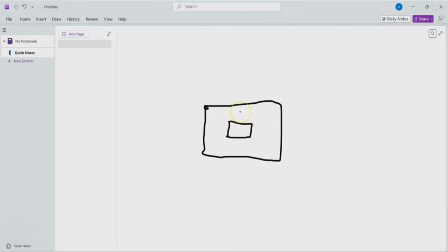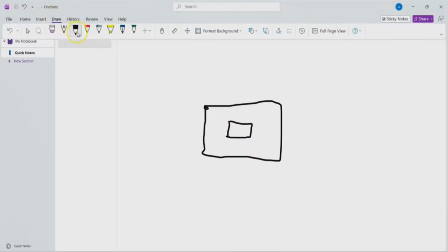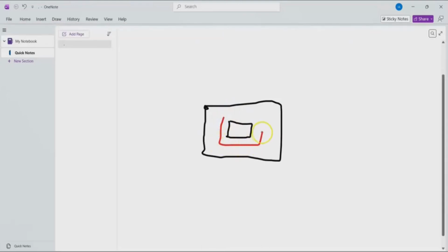Now, for two-way shear, that is the punching shear, the critical section for two-way shear is usually at a distance of d over 2 away from the face of the column. That is the perimeter of the column. So it's going to be something like this distance, because the column is trying to punch through the footing. So at the distance of d over 2, we are going to have the critical section, right? Which is around this perimeter. So this is for the two-way shear, that is the punching shear.